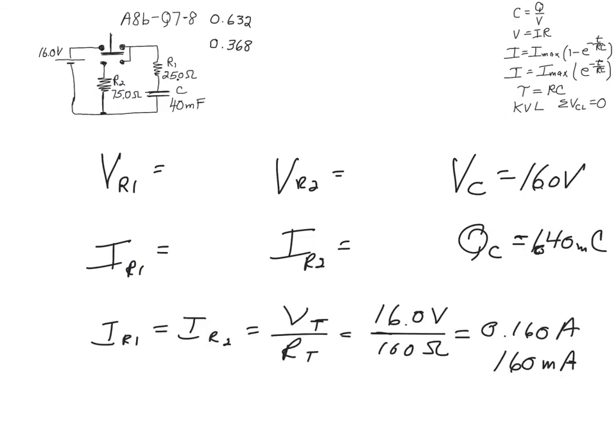Okay, very important. Start with the capacitor. Remember, that's the thing that can't change. So when the switch was up, it was fully charged at 16 volts. And so when the switch goes down, that will change, but it can't change instantaneously. That's the key issue. So that's where you start. 16 volts on the capacitor and fully charged, and that's going to decay.